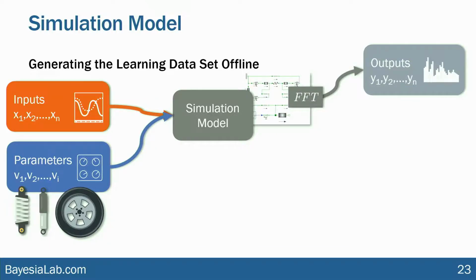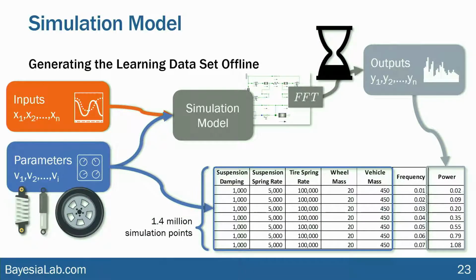run the simulation, sample that simulation with 100 samples per second, then perform a Fourier transform, so we have frequency data, and then compute the squared magnitude of the Fourier coefficient, which we record as the power of the signal, and that is shown here in the rightmost power column.